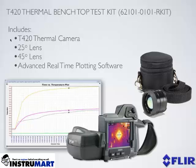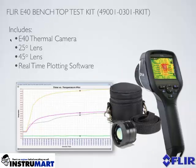And I will point out that that 45-degree lens that's included with this particular kit allows you to resolve down to 120 micron spot size, which is amazing. You can get very close and resolve very small targets with this particular kit. And there's a second kit available, the E40 benchtop test kit. This camera has a lesser resolution. However, it's still very powerful. It does come with a 45-degree lens as well that allows you to do close-up work to 200 micron spot size, includes real-time plotting and recording software, and will accomplish the task that I illustrated here today in our experiment.